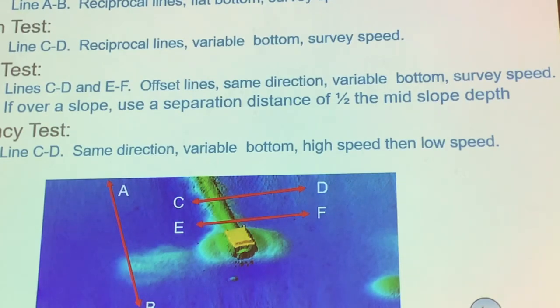How far from point A to point B? Oh no, you don't have to worry about how far. What's very important is that you need to have a very flat area, because when you are doing the calibration, you will see that you only use one swath. So if it's short, it's okay, but you must be perfect. If you have problem in that area, then you have to redo again. So what I normally suggest to everyone is maybe use about 50 meters.